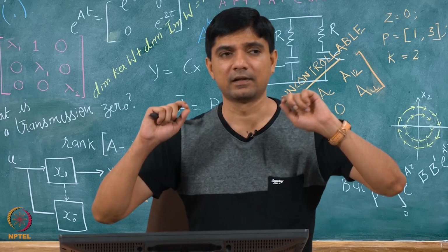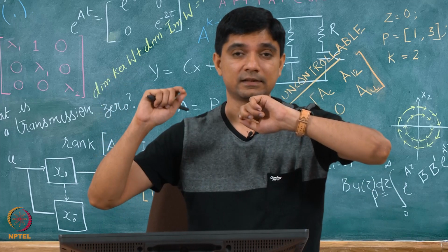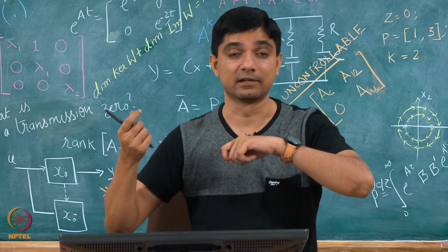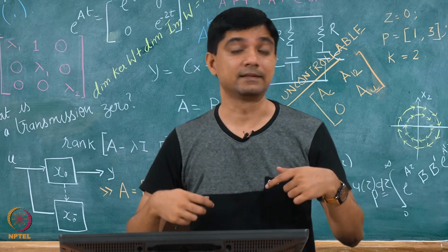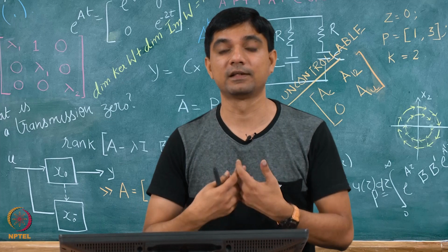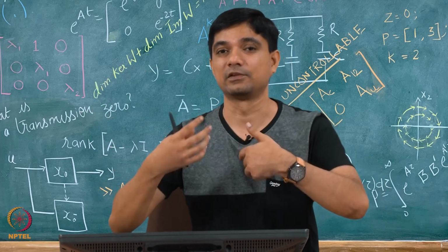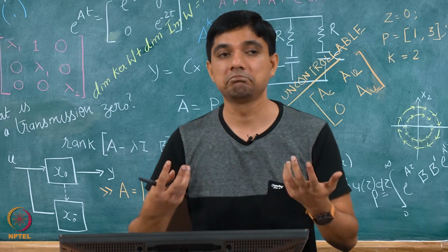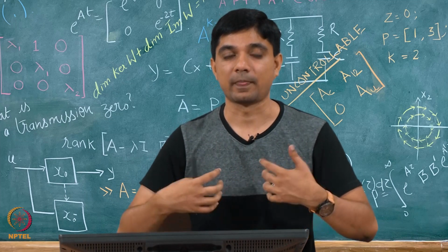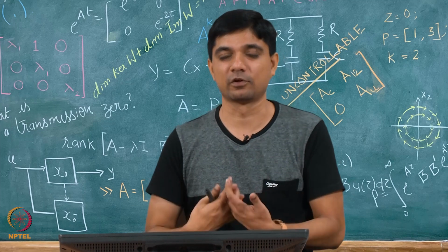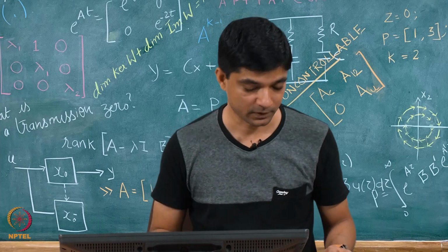It's something analogous to the Lyapunov matrix equation that we had, A transpose P plus PA is minus Q. But does the solution always exist or not? This depends on whether the system over there was stable or not. It will also depend here on whether the system is actually controllable. The solution does not always exist, and we possibly will see problems where the solution may not exist.